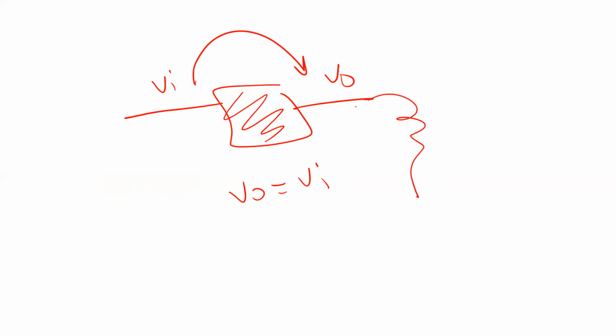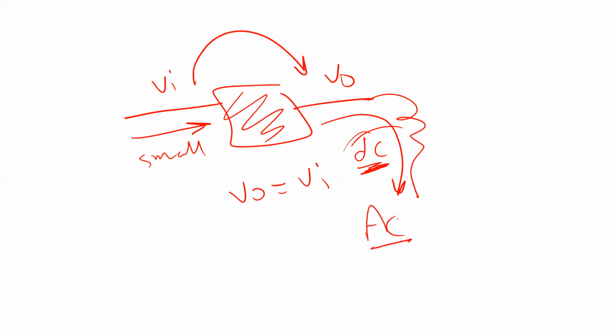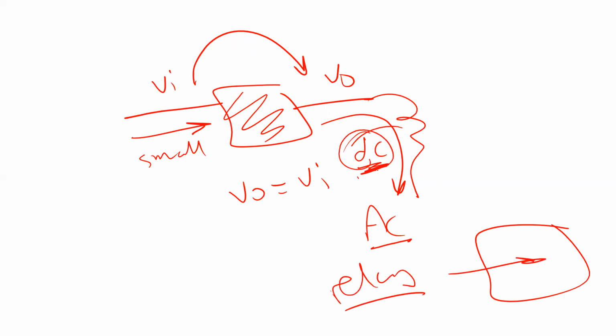Not only that, this one here is going to take a small current from here, and then it's going to drive a big current here. Still DC current, a big current. Even if this current is big, it is still DC. It cannot be AC. Also, this current is not enough if you are talking about a big motor. That's why you also have to use a relay in this case, because this current is not going to be enough to energize the big motor.